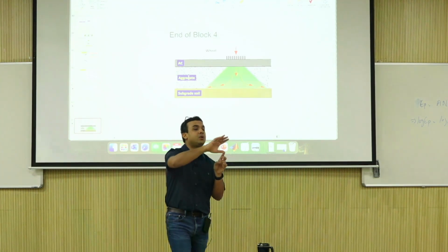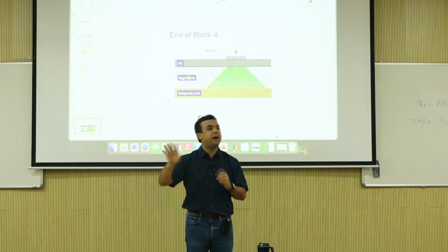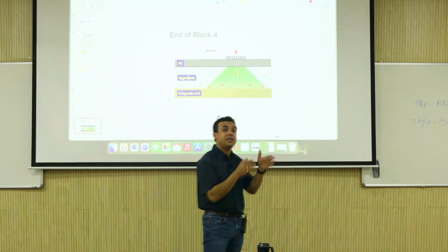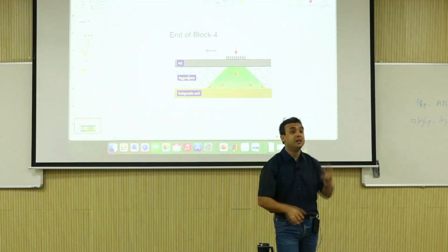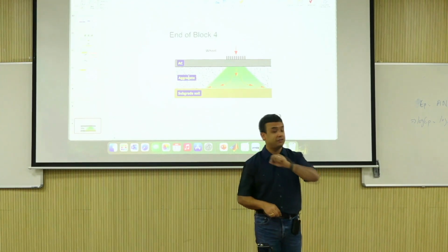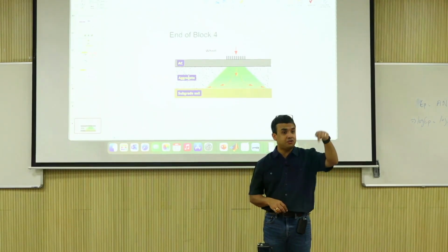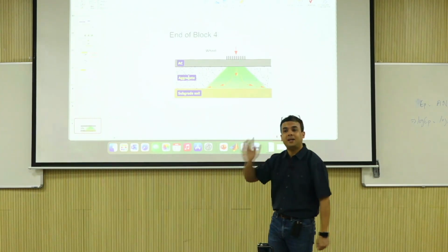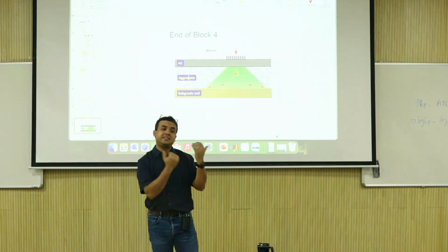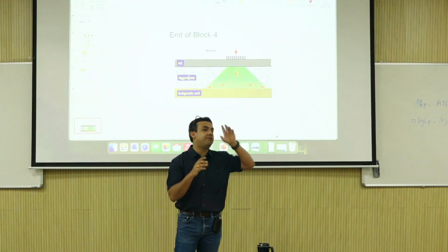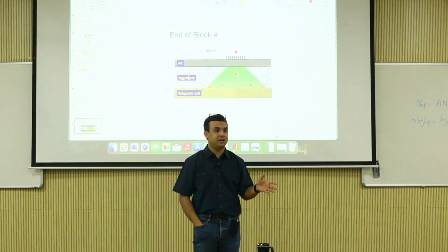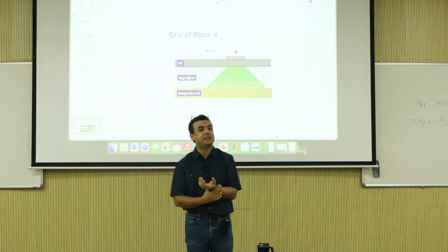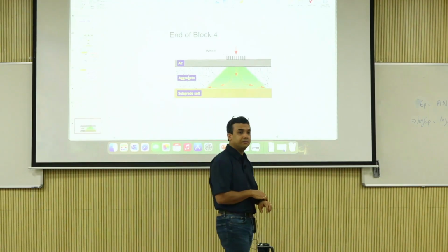So when you are running resilient modulus tests, you can get by without running a shear strength test. But if you are doing any study on rutting, like you are doing study on shakedown, shear strength test is a must, because otherwise you have no idea what your stress states are with respect to the strength of the material. You have to quantify it as a percentage, saying that this is the percentage where I was and that is what it is. Because the first question anybody will ask when you're doing rutting study is, what's the strength? At what level of the strength are you loading it? Because that's very, very important.